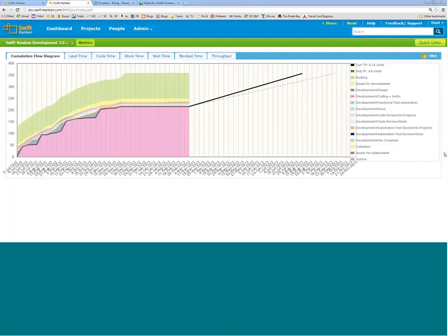And to add to that, the simulation engine has lanes which are configurable, and those lanes can represent the various stages of a construction project, like the plinth level or the slab that you are filling in. When you assign your primary and secondary resources to them, the simulation engine can predict when and how to apply those resources to the construction project and how soon it can be completed.